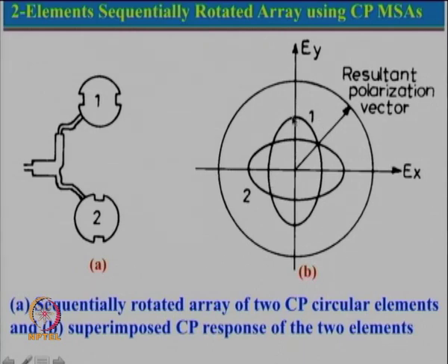So, at lower frequency, this will be the pattern for 1, I will just repeat. Here at lower frequency this is dominant, so that is why vertical component is dominant, and since some radiation will be occurring because of this, even though it is not fully resonant, it is partly resonant because this dimension is relatively closer to this dimension. So, it will give us a somewhat elliptical polarization.